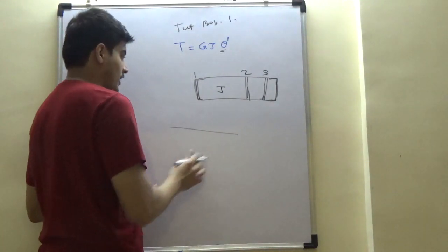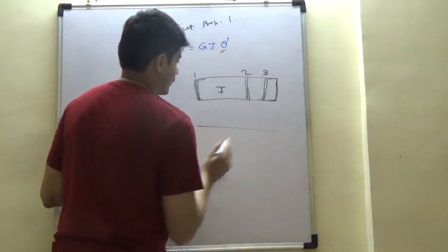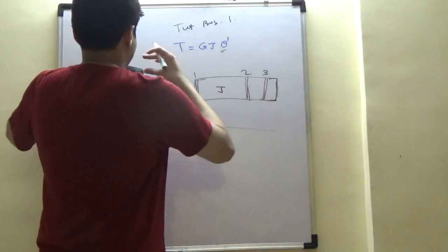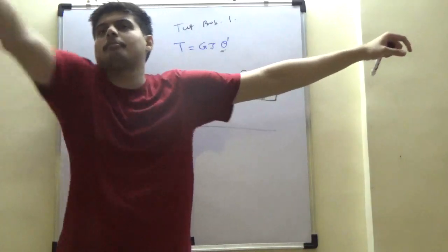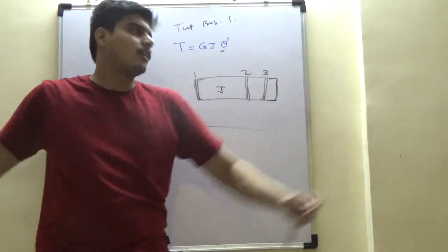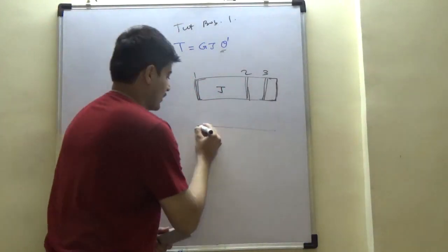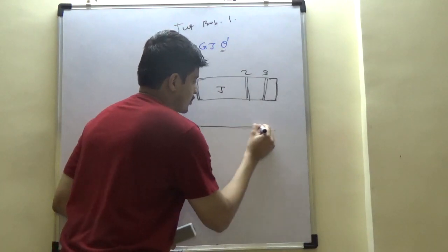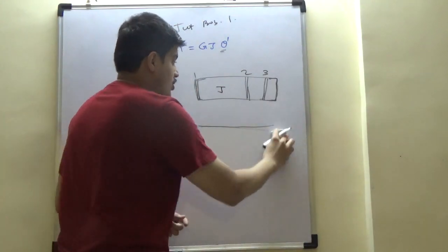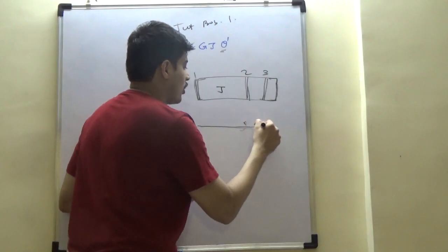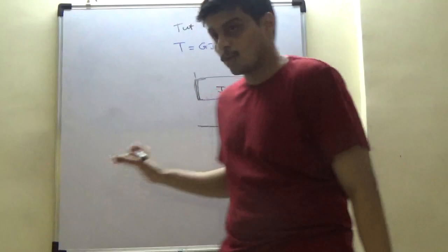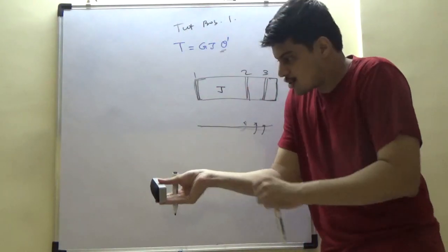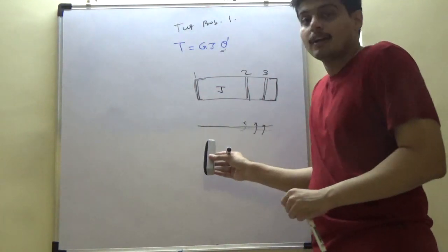So if this was my initial sectional view, the view from this side, if this is the aircraft which is parked, I am looking at it this way, almost like a line, right? It is going to have this twist, and this twist is going to cause each of these 3 sections, section 1, section 2 and section 3, to actually increase in their angles.